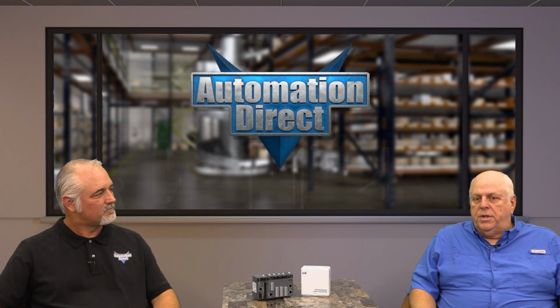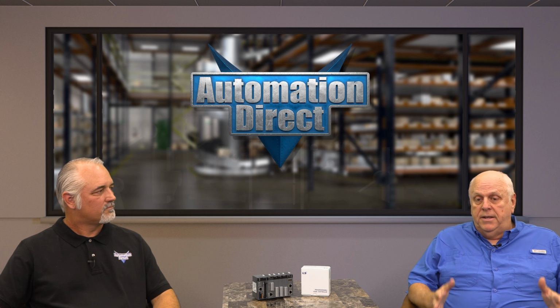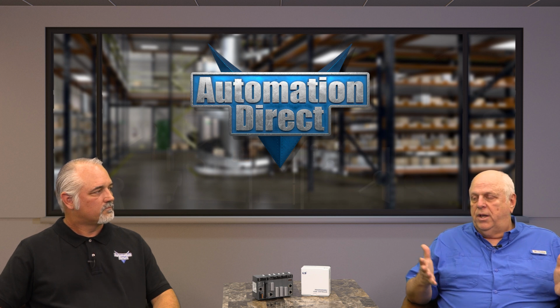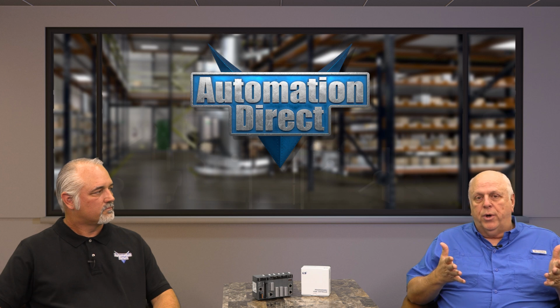So Shane, what they did was CODESYS takes it to the next level, so to speak. With IEC 1131, you have to use the vendor software with their hardware. IEC 1131 gives you the base, but they can have add-on instructions and such. CODESYS says, we have one software package and we're going to download to multiple hardware platforms. Like you folks, you made a CPU for your Productivity PLC. So I can take out your Productivity PLC that works with your software, pop in a CODESYS CPU, use the CODESYS IEC 1131, and it works.